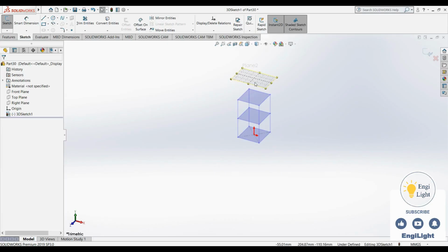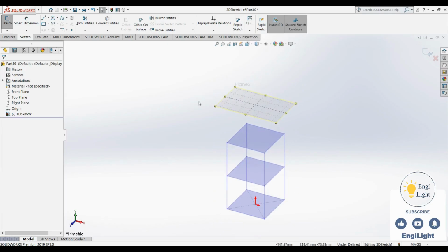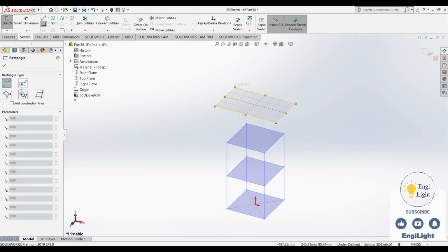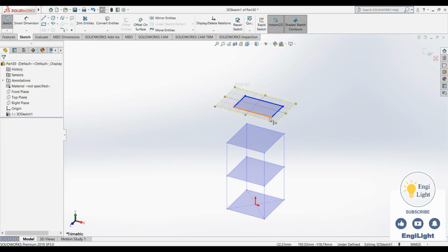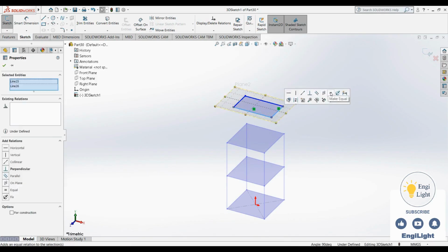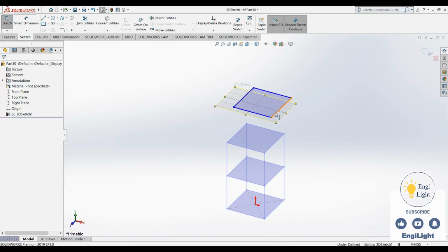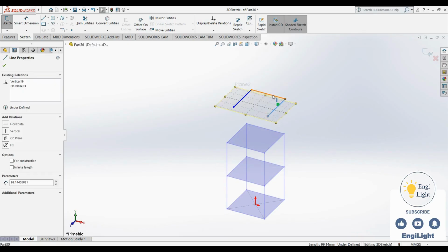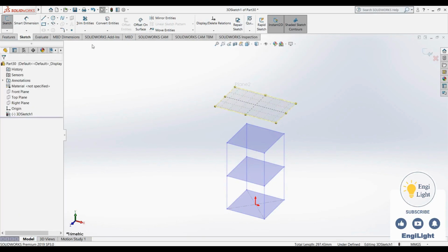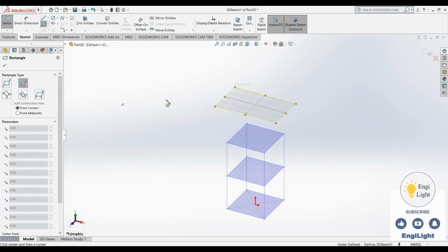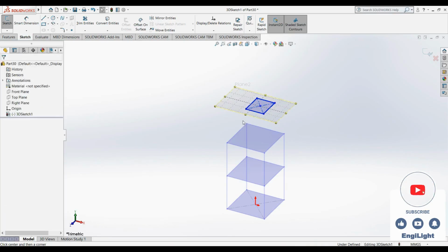So the plane is created, and from now on, all sketching will be on this plane. I select the rectangle tool again, and using the first type, I draw a square here. I convert this rectangle into a square by applying the equal relation. Actually, let me draw this shape using the second type of rectangle tool. So, rectangle tool, second type, like this. Well then, in the next step, I turn this into a square.